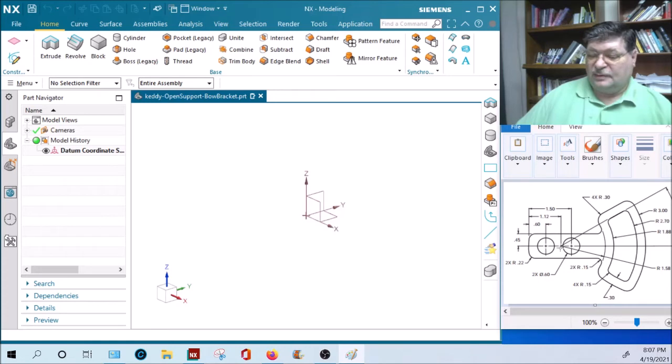They're all concentric, or they have a coincident point, you could call it. Okay, the centers are all coincident. That line has to lie on that center, otherwise it will not constrain, it will not look the same. So there's a geometric constraint we have to take into account also.